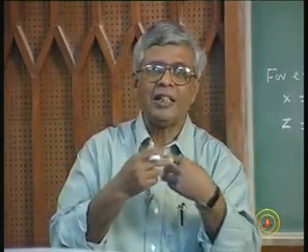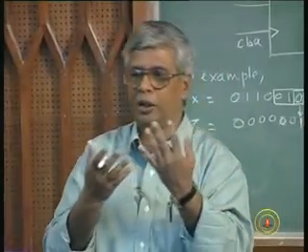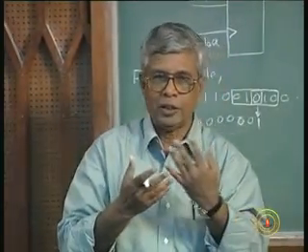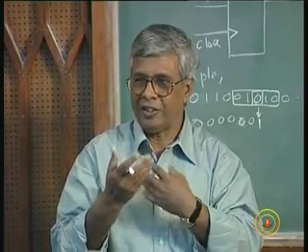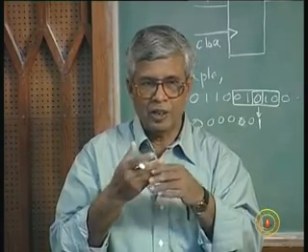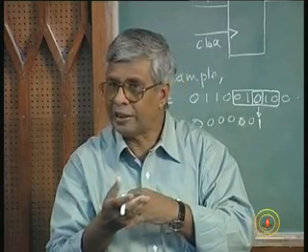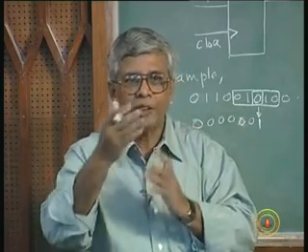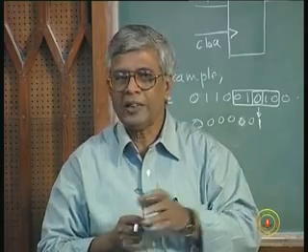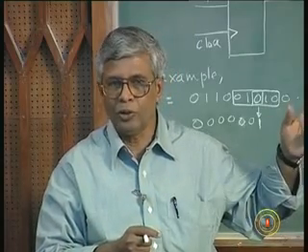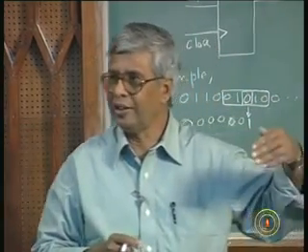See, all these should be very clear in the specification. You can't just jump to the design board or the breadboard as soon as somebody tells you a problem. If the problem is vague, you should ask questions. Everything should be clear. Should it be a Mealy machine or a Moore machine? Do you want overlapping patterns also to be detected, or only clear patterns to be detected? All those questions you should ask beforehand, because your circuit will be vague otherwise, and because you should always understand what the person wants before you can go and design the circuit.